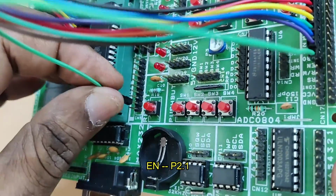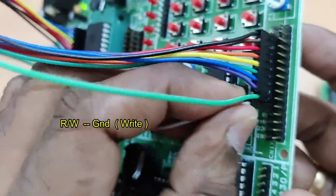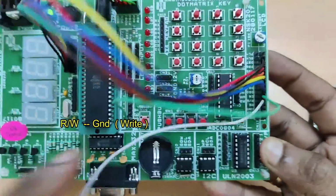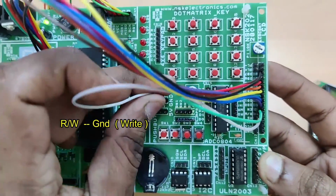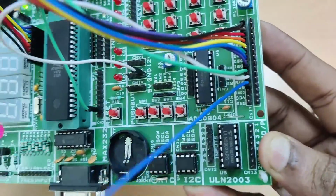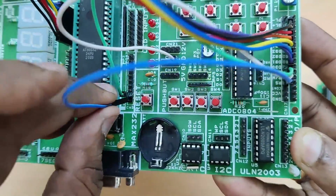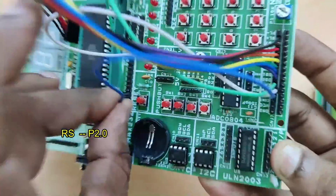And next is the read write pin. It will be grounded permanently, since we are going to use the LCD in write mode only, so we can directly connect the RW pin to ground. And the next pin, RS control pin, goes to P2.0. So this is the connection.